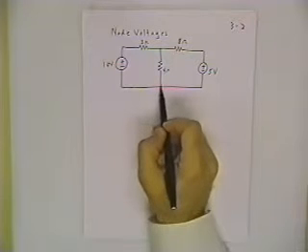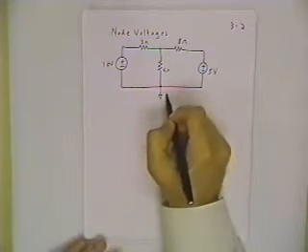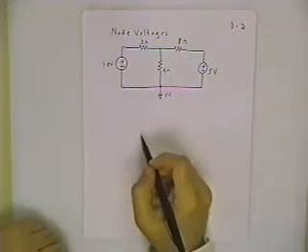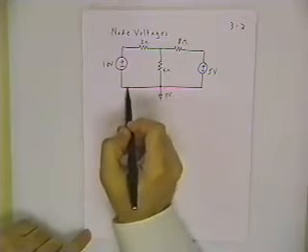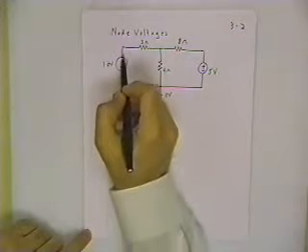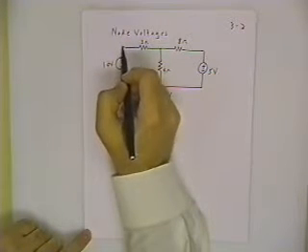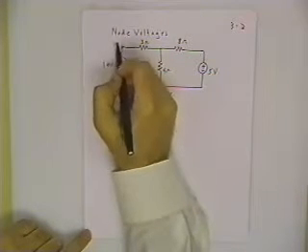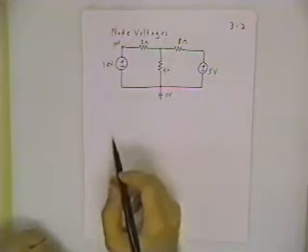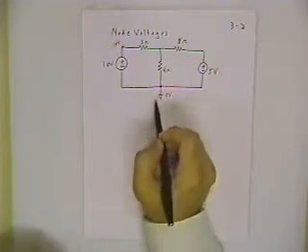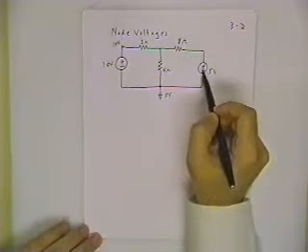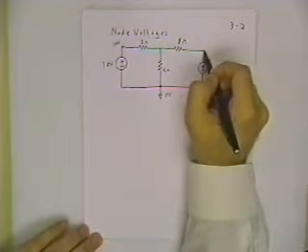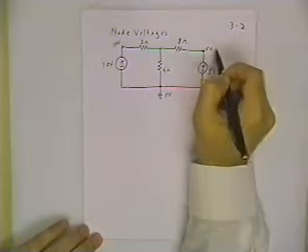Well, now if this is ground, that's what we call zero potential. That tells me that if I'm a positive test charge and I go through this 10-volt source in this direction, I wind up at this node and I have 10 volts more potential than I had when I left ground. Following a similar path here through the 5-volt source says, well, if I get up to this node, I've got 5 volts of potential.